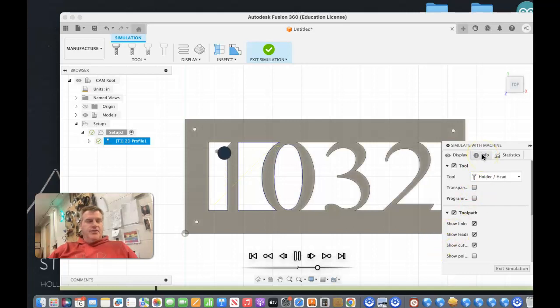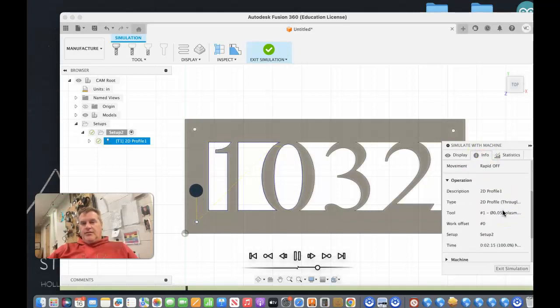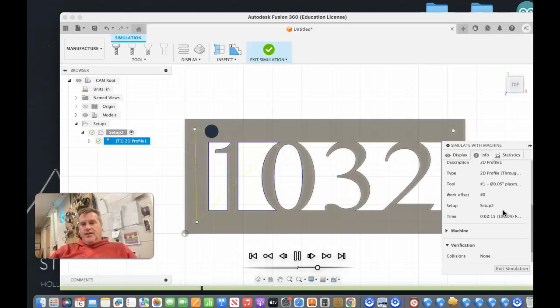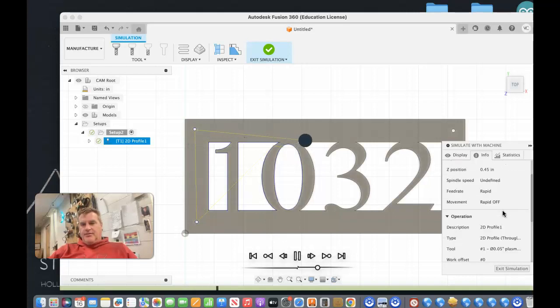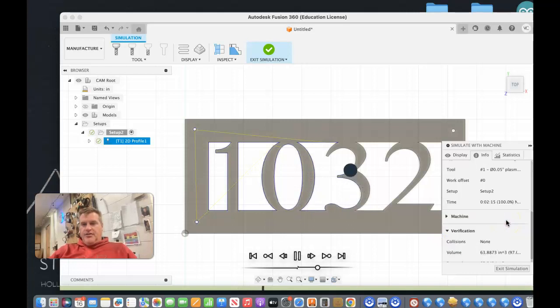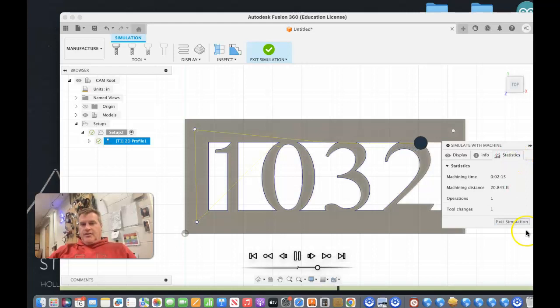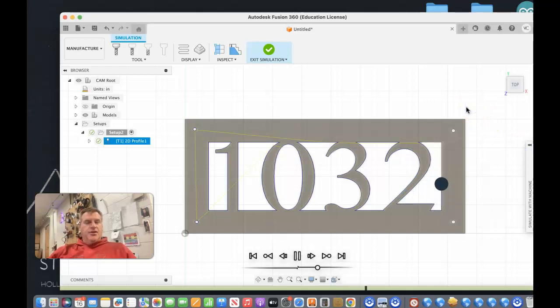One thing I did find, which is kind of cool, you can go into info, and it's showing you the stuff going on. See if I can scroll down. I was seeing a time, and I'm not seeing it right now. I like seeing the feed rate is at 100 inches per minute, so that is all good. Oh, right there. Cool. Time 2 minutes and 15 seconds to actually cut this thing out, which is not too long at all. Okay. Stats. Yep. Machine time 2 minutes and 15 seconds. So that's kind of cool to go ahead and see that.